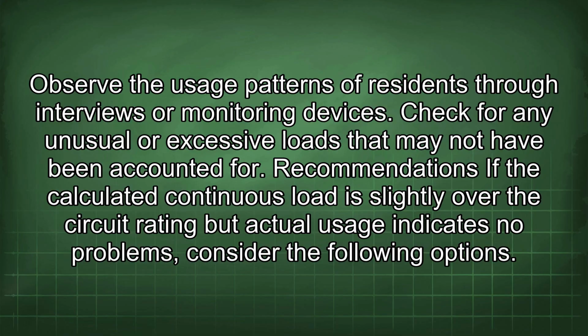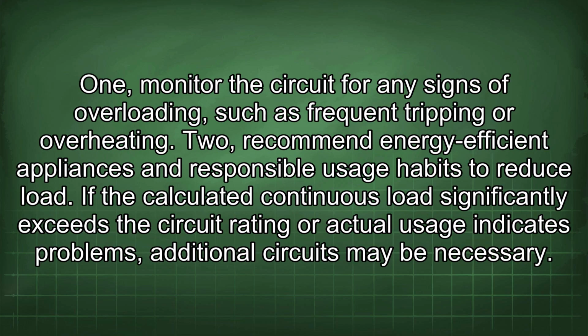Recommendations: if the calculated continuous load is slightly over the circuit rating but actual usage indicates no problems, consider the following options. 1. Monitor the circuit for any signs of overloading, such as frequent tripping or overheating. 2. Recommend energy-efficient appliances and responsible usage habits to reduce load. If the calculated continuous load significantly exceeds the circuit rating or actual usage indicates problems, additional circuits may be necessary.